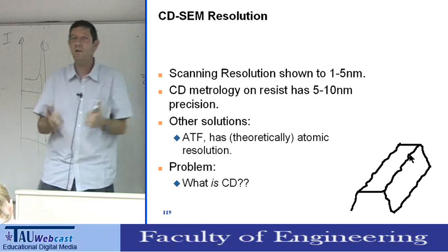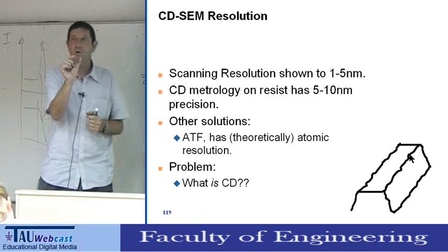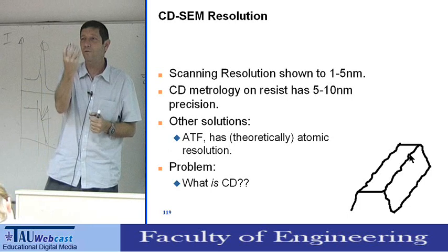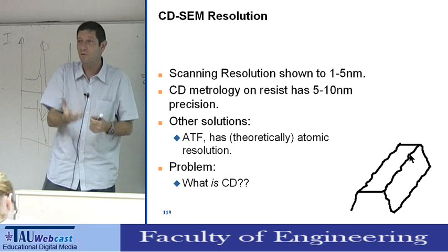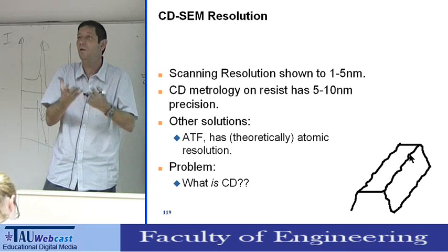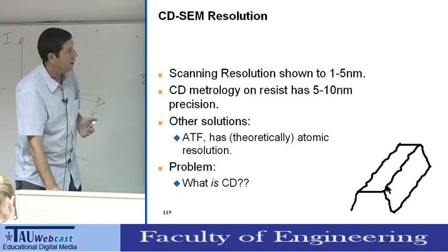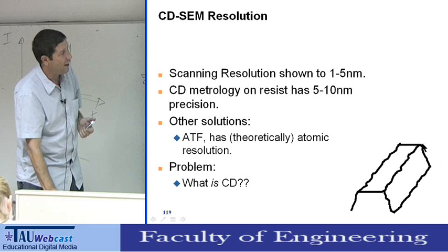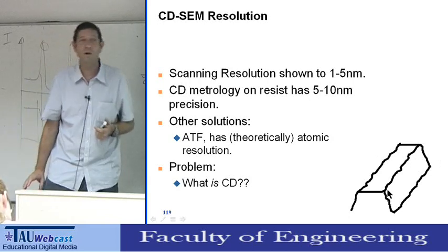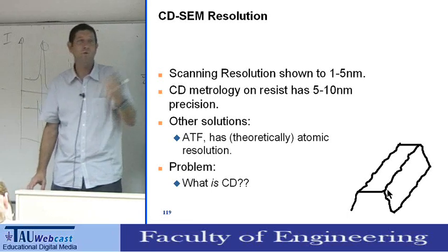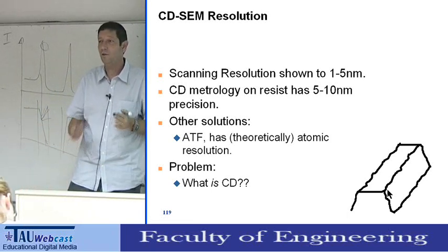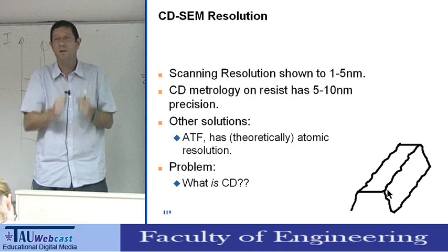For example, one of the issues is that because the volume is so small, the number of photons reaching the substrate is also a very small absolute value. And this problem of line edge roughness is a very big problem, because first, if you have this roughness, how do you define the CD? Is it on the narrow line or the wide lines?